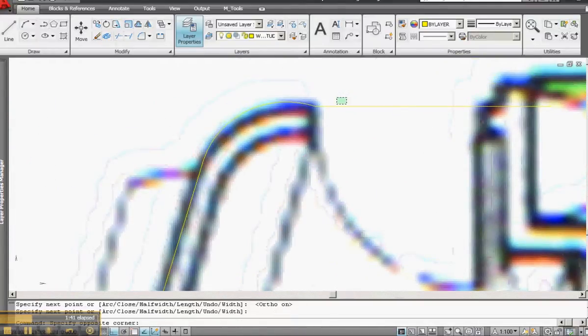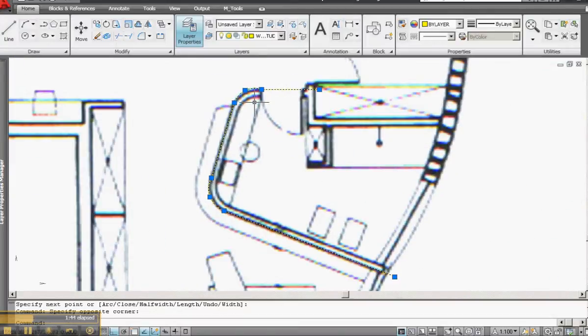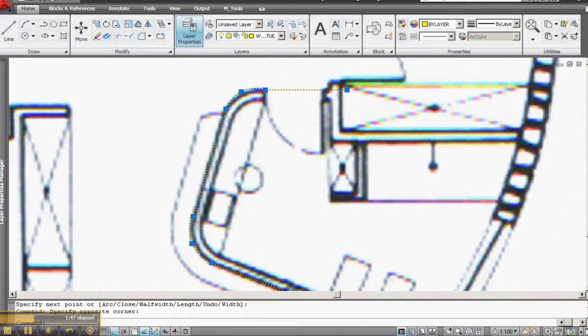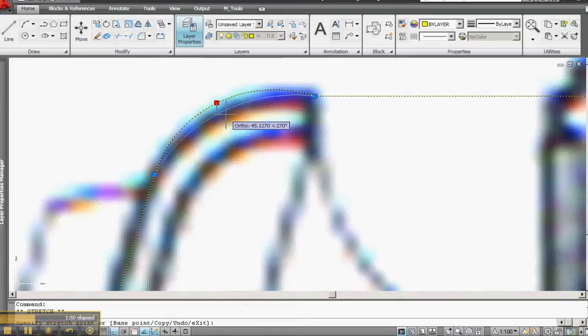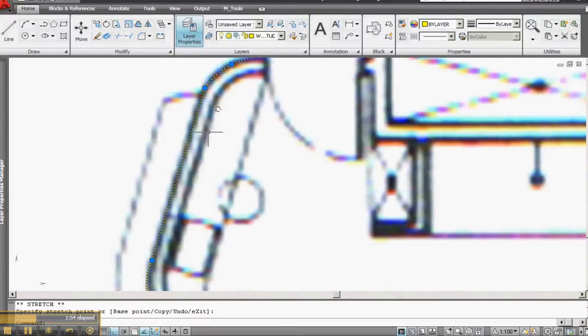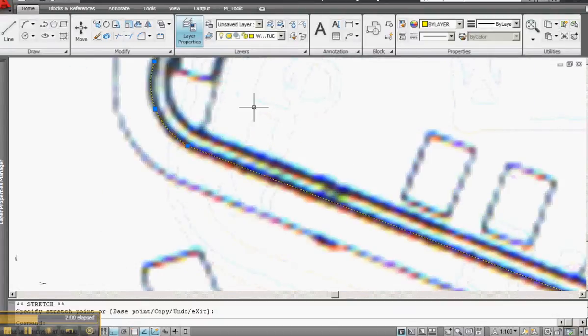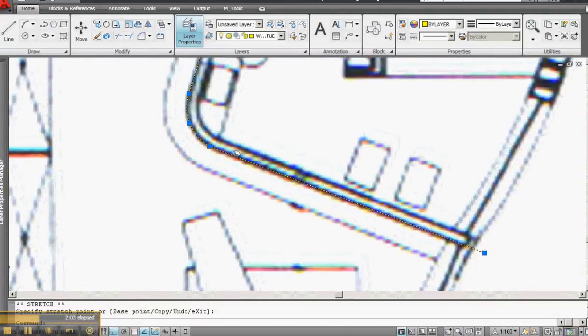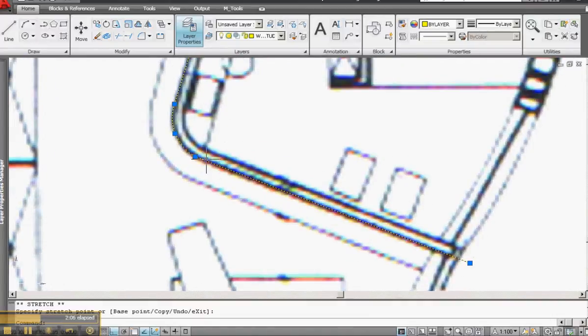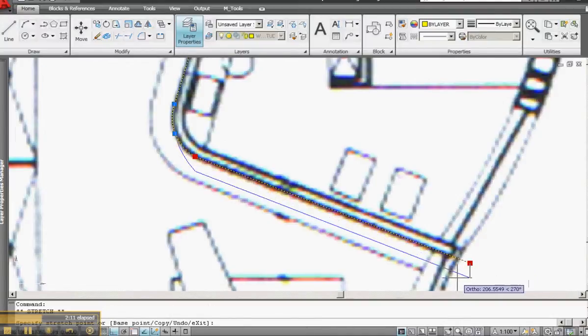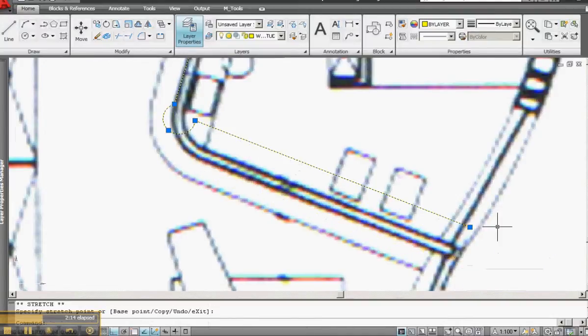Now you can go in and select that line, well, it's actually a polyline, so all of those bits of line are joined together, and then you can edit using the grips by just selecting the blue grips and dragging them around like so. And say we wanted to select multiple grips, say both of these guys need to move over a little bit, you can hold down Shift and move multiple grips together, and it'll do some weird stuff. So undo that, which is just Control Z or U, enter.